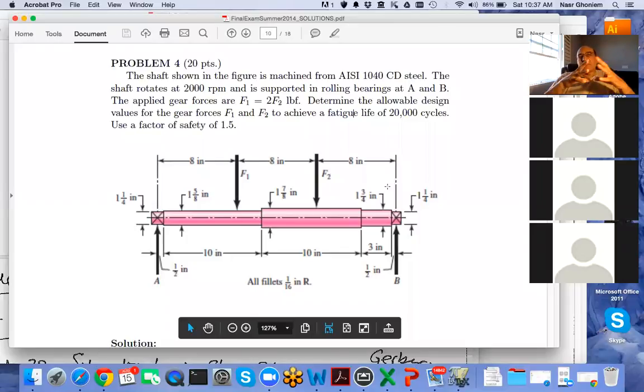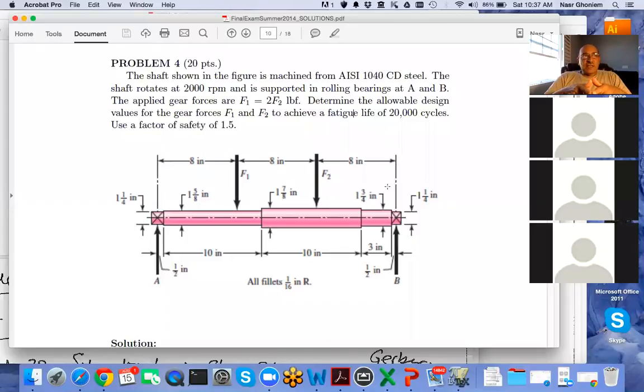What happens if we have real gears, as you'll see in this week and the following week? When you have real gears, the force is transmitted through some contact line, and the contact line is never perpendicular in the vertical direction. It actually has a pressure angle. Every gear is designed with a pressure angle, usually around 20 degrees from the horizontal. So the force is actually coming at an angle, right? So what do you do about this case?